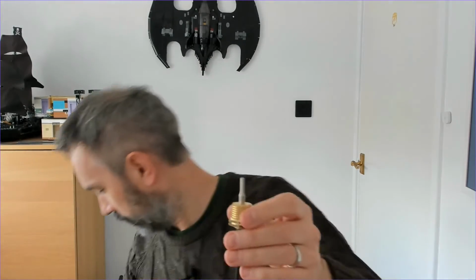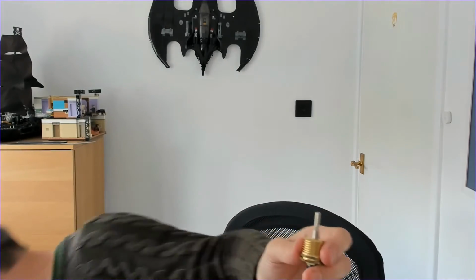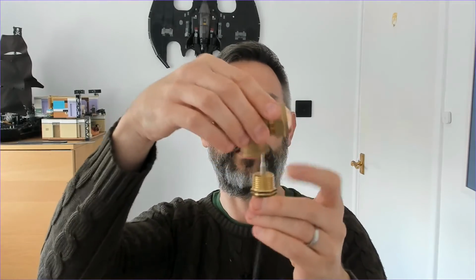On the outgoing side, there's another probe. There's a little T-junction. If I just grab that, just to show you. So there's a little T here with a slot on it, and then this probe is for the flow temperature. So this measures the temperature of the water going out of your boiler. So essentially this just fixes in and measures the water, and that's how the heat meter can then work out how much heat is moving around.